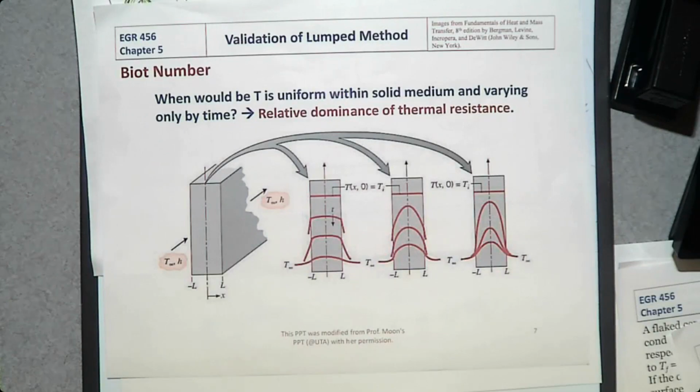Not really. If I were a lumped system, my body temperature would go down dramatically and I'd be a dead body, right? I'm not a lumped system, so my heart stays at high temperature and I survive. Then how do we know how uniform the surface and the temperature of the solid should be to be assumed a lumped system?